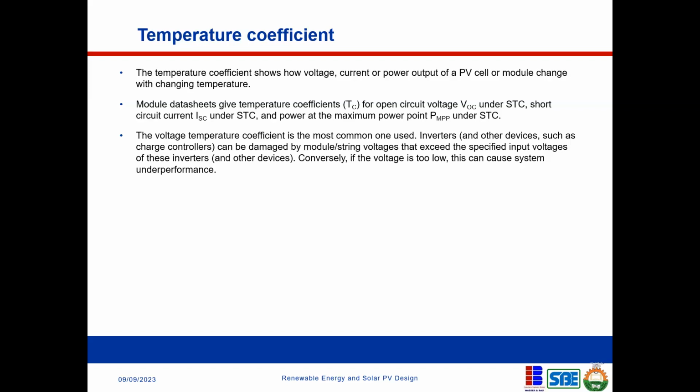You could put what do you call it, AVS, a voltage switch, so that if the voltage gets to some certain unwanted limit, it just cuts off the supply into the system. So voltage is very, very important. I'm just stressing this to show you how important voltage is when you're doing your installations. So the equipment can be damaged because of voltage if it exceeds the limit.